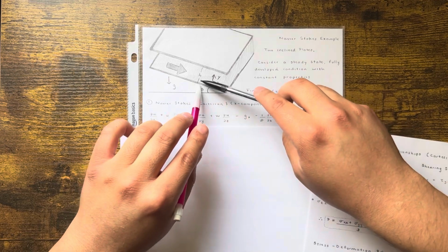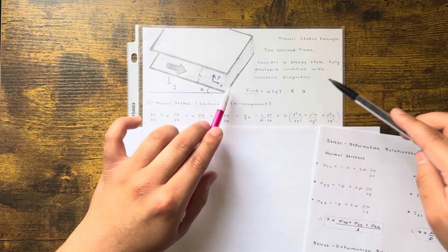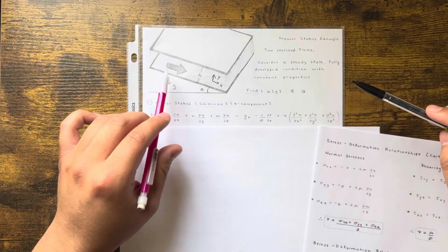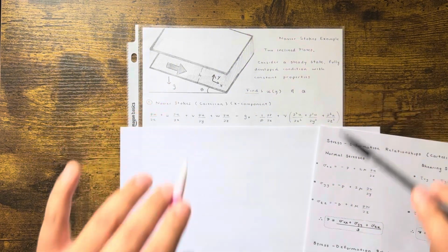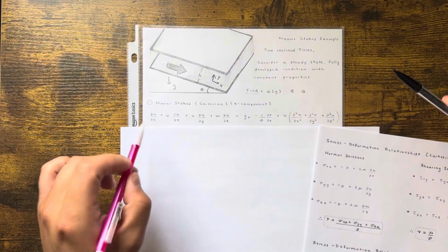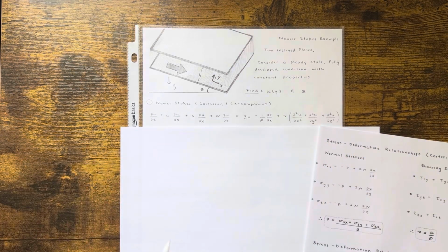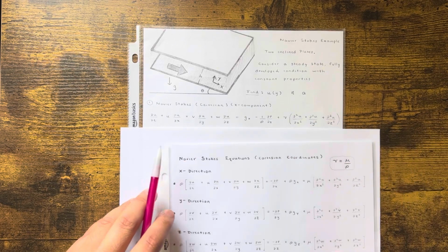So it's at a height h. It's tilted at an angle, fluid's in the positive x direction. There's nothing going on in the up and down direction. You have two infinite parallel plates going into the page. The x component for the Navier Stokes equation in Cartesian form is just this, and this is what I like to use.